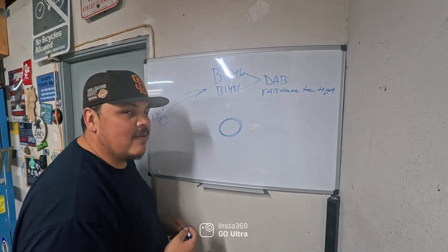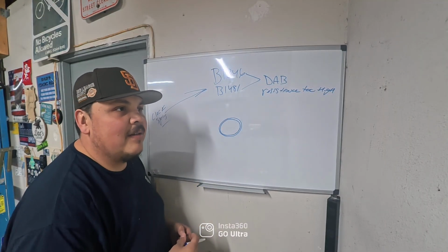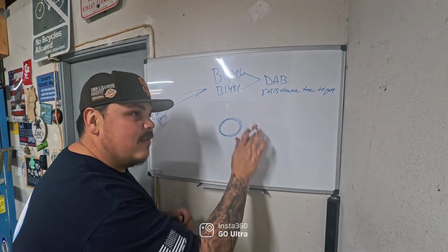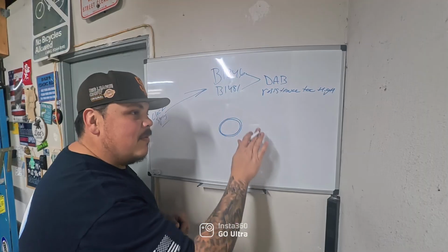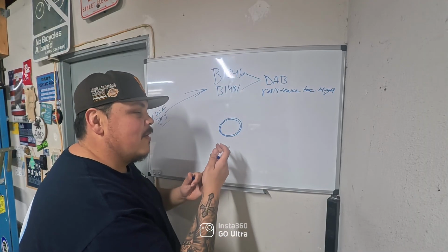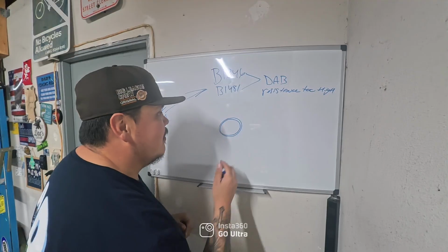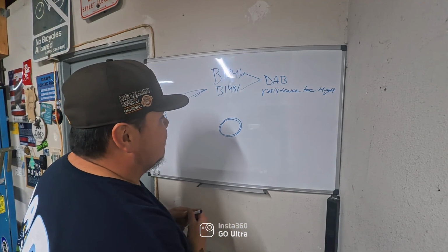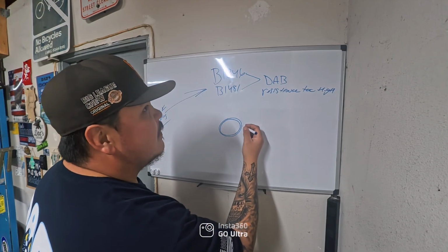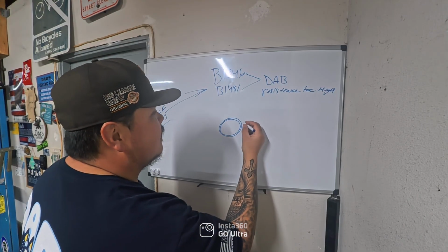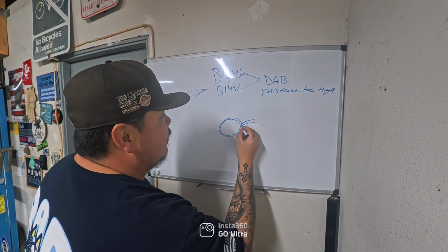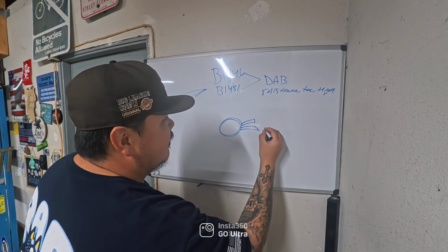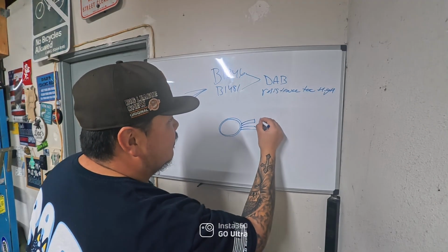Your horn button, your steering wheel buttons, your driver airbag, all that stuff goes through the clock spring, and that's the way that the steering wheel is able to stay in contact with the wires and still be able to be turned. So it's a band type of wire harness. I think it's a 4-channel airbag circuit. So you have 2 connectors. I believe it's a high and a low.